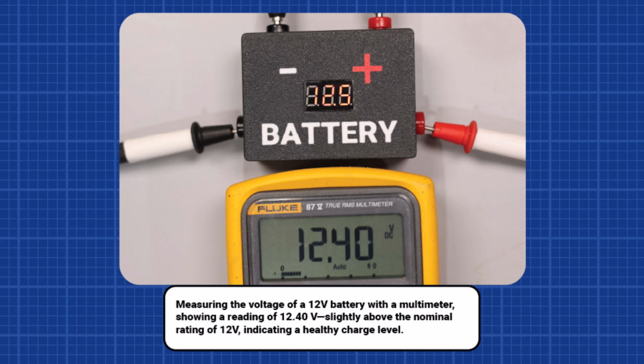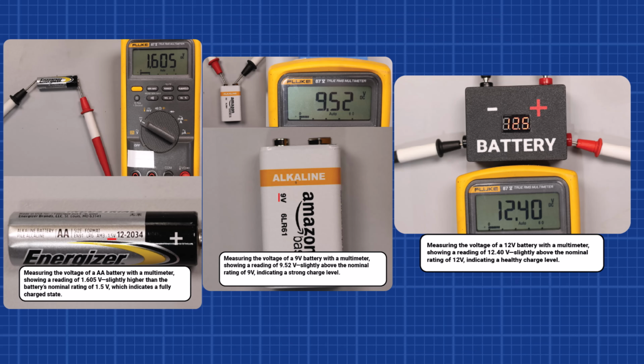These measurements give us an indication of each battery's charge level and general health. For example, a AA battery reading of 1.6 volts, the 9-volt battery reading of 9.5 volts, and the 12-volt battery reading 12.4 volts all suggest that these batteries are freshly charged. However, voltage alone doesn't fully verify a battery's ability to supply power under load. To thoroughly assess a battery's condition, factors like capacity and internal resistance would also need to be evaluated.